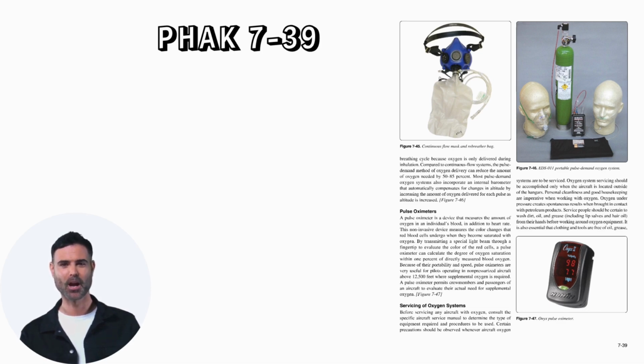Most pulse demand oxygen systems also incorporate an internal barometer that automatically compensates for changes in altitude by increasing the amount of oxygen delivered for each pulse as altitude is increased.